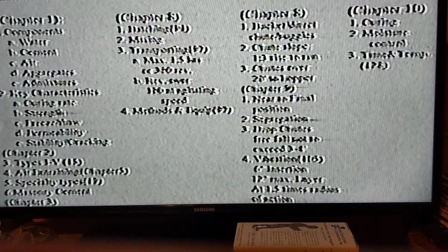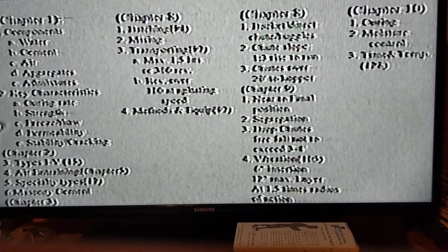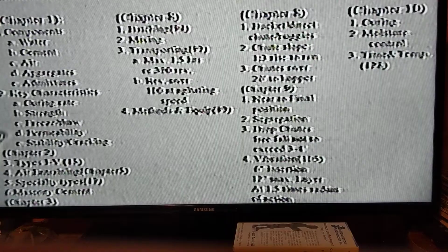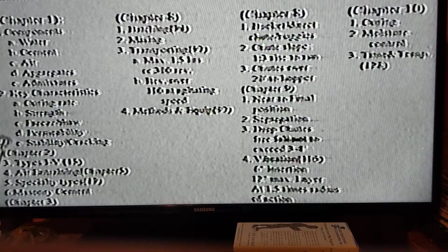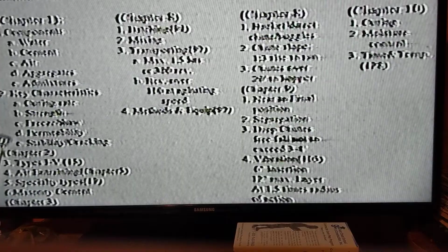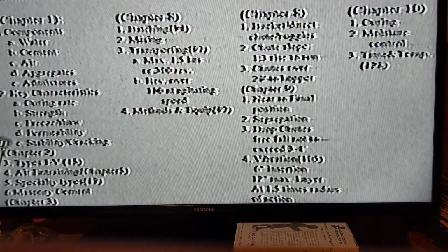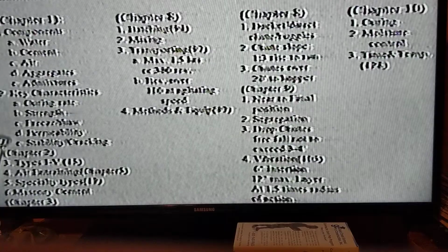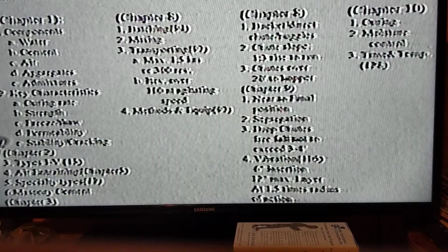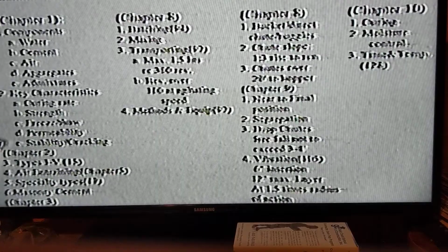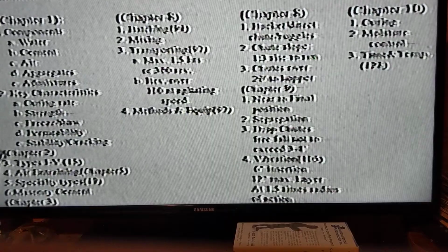Now there are certain key characteristics of concrete that get measured. The first is the curing rate. The second is the strength. The third is the freeze-thaw cycle. The fourth is permeability. Now permeability relates to the durability of the concrete. The more permeable the concrete, that is to say, the more open it is to be infiltrated with other substances, well, the more that other substances are going to infiltrate it and break the concrete down. So permeability is an issue that deals with longevity. And then we have the issue of stability and whether or not the concrete is going to have a tendency to crack.